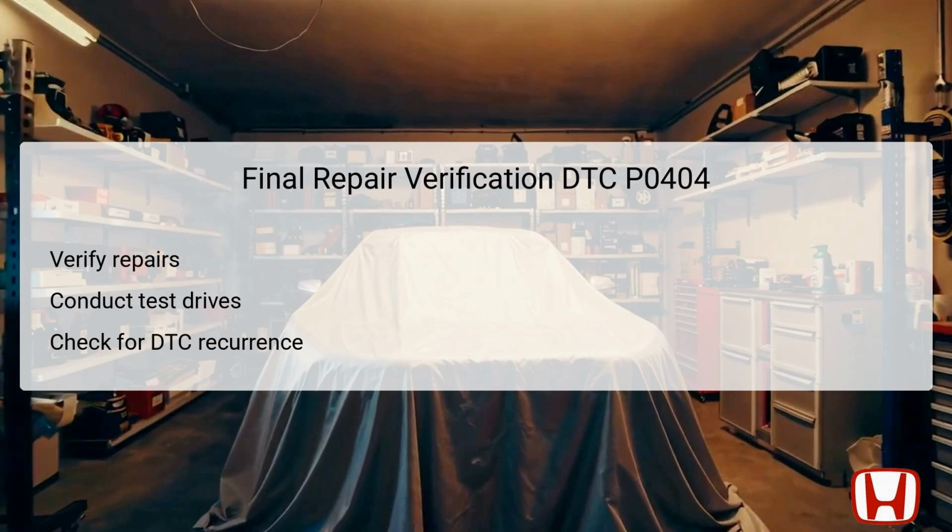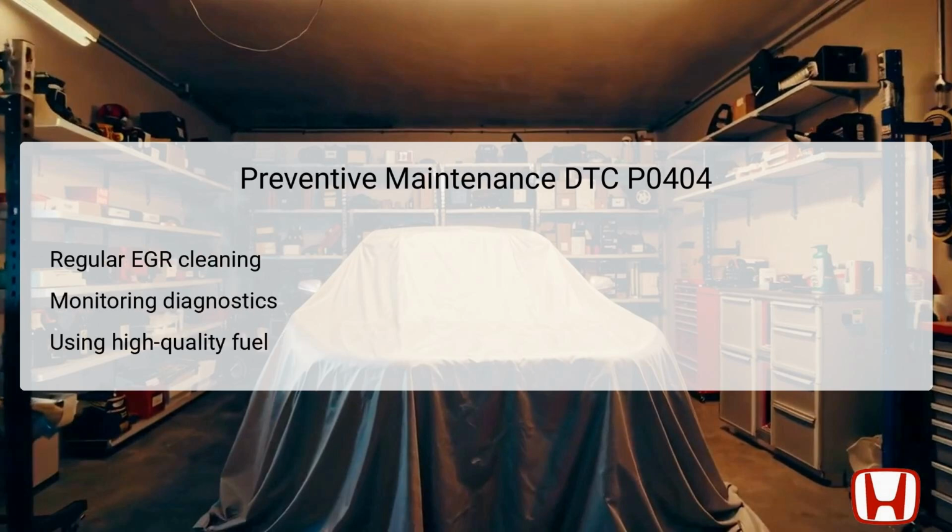the expected parameters. Preventive maintenance is essential for minimizing the future occurrence of DTC P0404 and ensuring ongoing vehicle performance. Regular cleaning of the EGR valve and its passages can significantly reduce the buildup of carbon and other deposits, which helps maintain optimal operation.